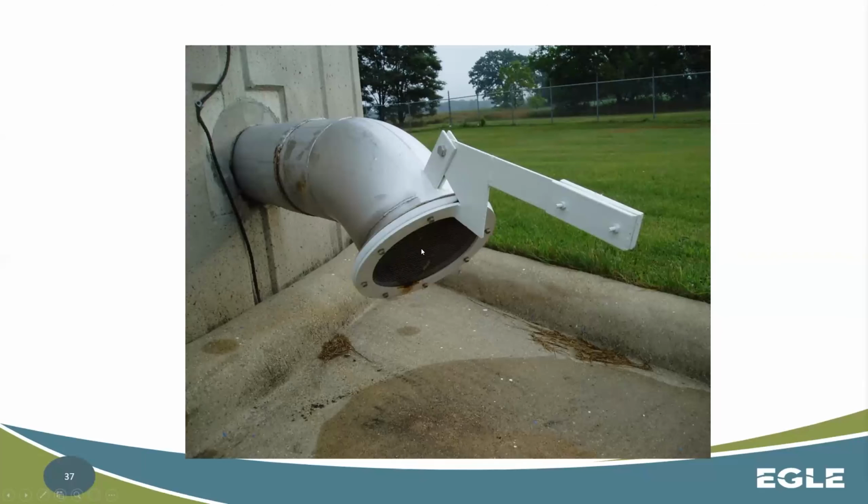So as cold air whips through, it's going to go up and come across the top of that tank and really cool down the top of that water. And basically that's going to be promoting ice formation at the top. So you might have an ice cake at the top that can cause damage to your tank in lots of different ways. It can cause vacuum issues, pressure issues, things like that. And just ice formation in general, maybe it's too much and it fills the whole tank.